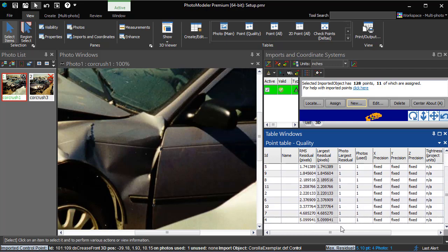Unlike standard reference points, in this project, we're solving the camera parameters using control points that are set so that their coordinates cannot be adjusted. If we're not fully confident they are marked in the correct position, this can result in higher point residuals. For these types of projects, residuals around 10 pixels are acceptable, but lower would be better.